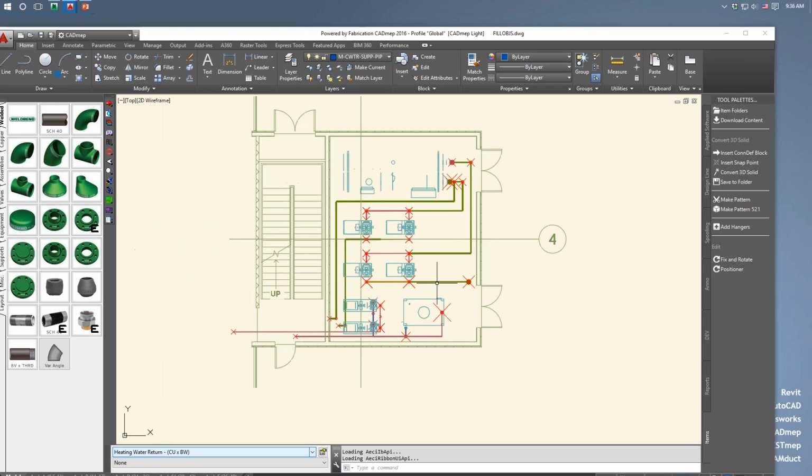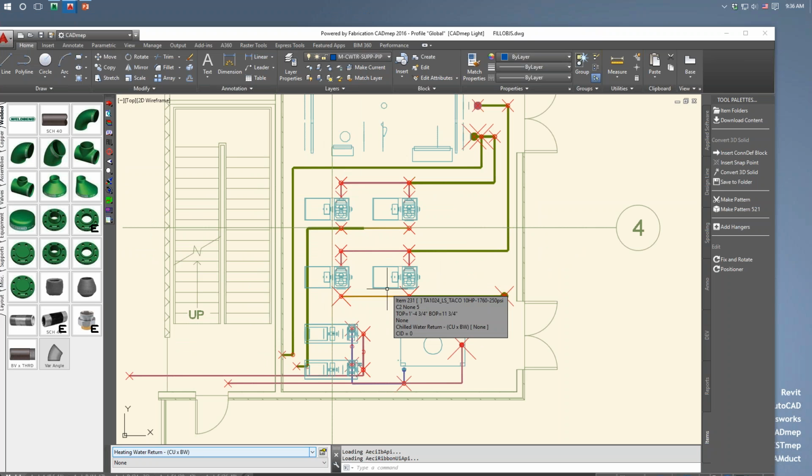When I'm drawing with design line, a lot of times I'm not filling them. I'm just working on them, especially when they get big, they take a long time to fill. So at the end of the day, I have all these design lines that aren't filled that I have to go through. In the past, I go through and double click each one and then fill it so that I can save it. But I have a command just for doing that that works even better. So it is fill design nodes.